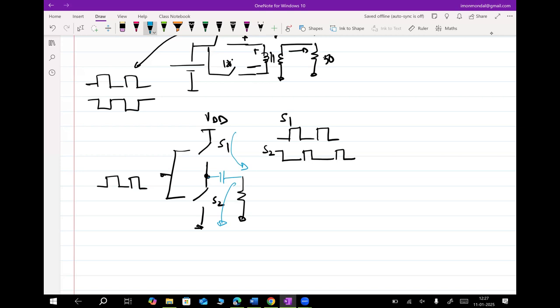If I neglect the leakage current or the VDD to ground switching current, then there is no loss. So in principle, in theory, you can postulate that these type of power amplifiers, which are essentially inverter based, can give you 100% efficiency. We can prove it, but obviously there are losses, and that doesn't really help. Okay.